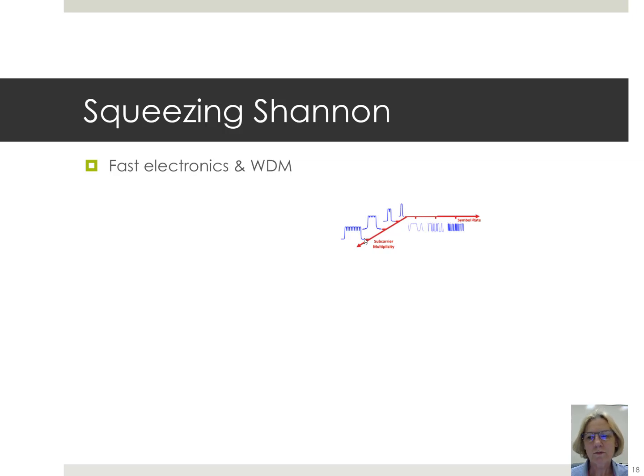Then we used multiple wavelengths. As we use more and more wavelengths, we're piling up in the frequency domain how many wavelengths we're able to exploit. So as the symbol rate goes up, each one of these channels gets fatter because I'm able to put more data on it, and then I sort of line them up.